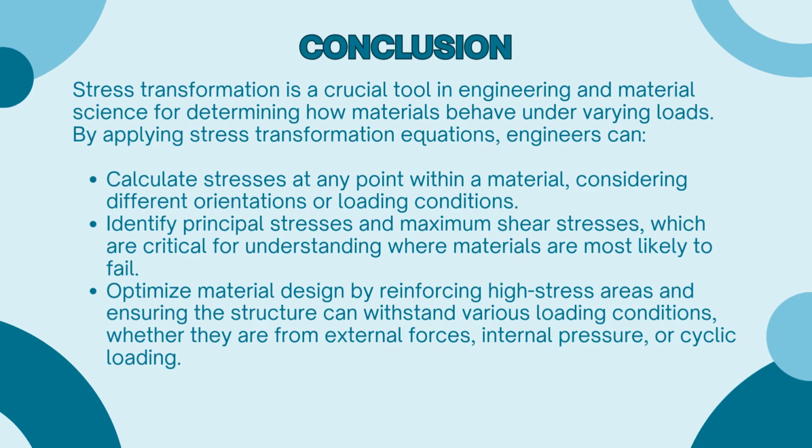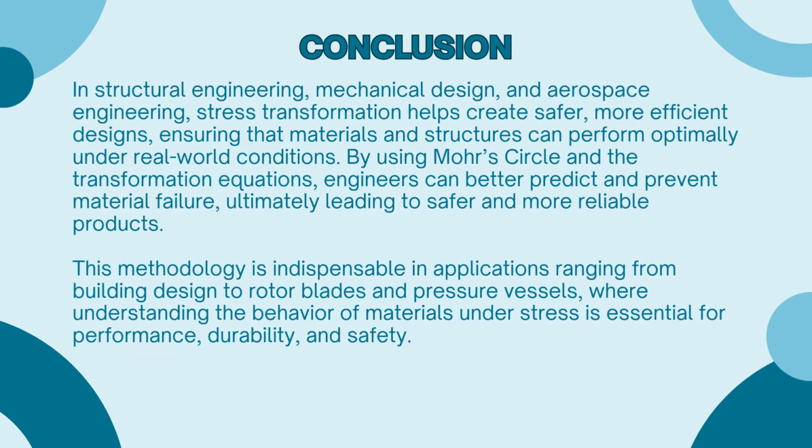Conclusion: stress transformation is a vital tool in engineering and material science. By applying stress transformation equations, engineers can calculate stresses at any point within a material, considering different orientations or loading conditions; identify principal stresses and maximum shear stresses, which are crucial for understanding where materials are most likely to fail; and optimize material design by reinforcing high stress areas and ensuring that structures can withstand various loading conditions, whether from external forces, internal pressure, or cyclic loading.